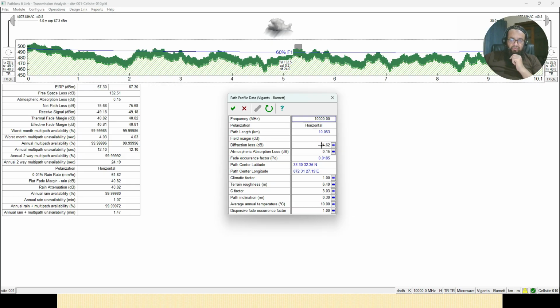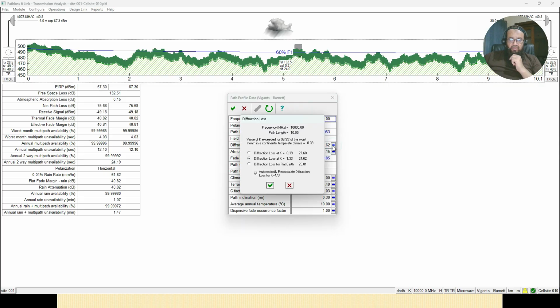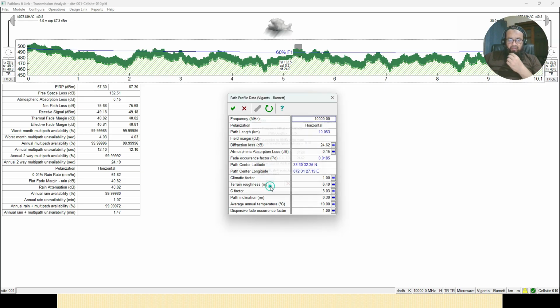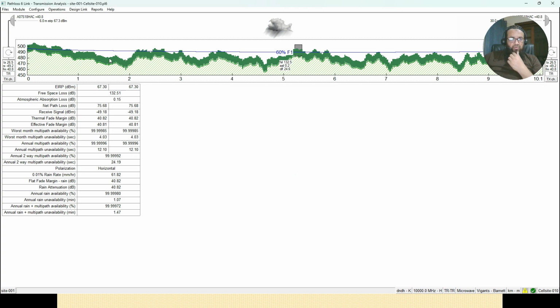I mean, it's not very much recommended. It's better that you ask path loss, but you can see here it's calculating it on different. Currently, it is on K is 1.33, but you can change it to different values and you can see the effects. I mean, when you change the K value, the effects change at the same point. And no, I don't want to make any changes.